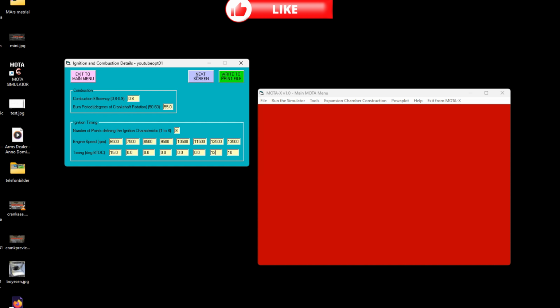And right here, it interpolates between the values, but I'll set 50 degrees. And now this is where the pipe starts to boost the engine. And it hasn't reached the maximum boost level, so to speak, so you can have a higher value. I'll set 20 degrees and 25 and 30, 30 and 30. Now we've got an ignition curve that isn't very strange, it's just a normal curve.